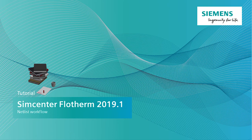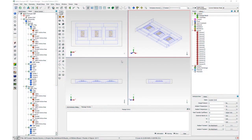Welcome to this video where I'll be showing you how to use the Thermal Netlist export functionality in Simcenter Flotherm 2019.1. For linear conduction-only models, a Thermal Netlist file, also known as a thermal spice file, can be created to a user-requested level of relative error. Combined with the electrical netlist, circuitfile.cir, an electrothermal circuit analysis can be performed in Mentor Eldo.